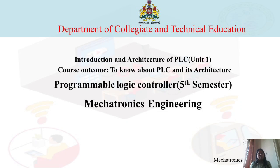Understood? After that, we have seen the differences between data processing computers and process control computers. Data processing computers are just like your normal computers. Your inputs are the keyboard, mouse, etc., and your outputs are VDUs, printers, plotters, etc. But for process control computers, the main inputs are switches and sensors, and the outputs are solenoids, motors, etc. So your PLC is an example of a process control computer.